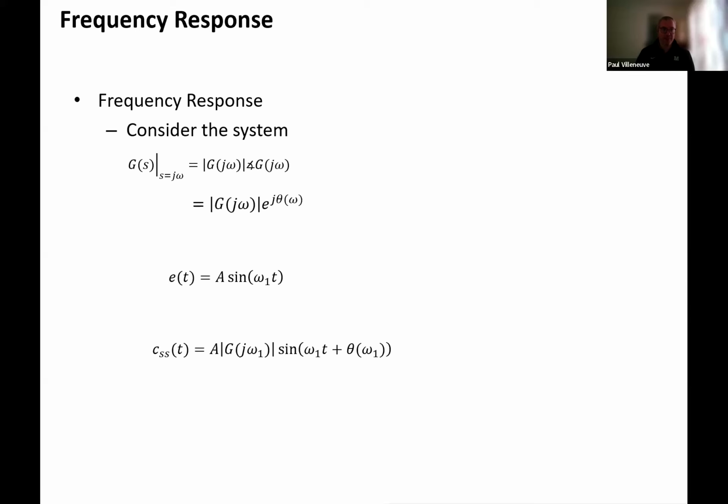That's why they're complementary. All right, so let's look at a system, any old transfer function. And we're just going to represent our closed loop transfer function. So if you want to subscript this with a closed loop, you can see that that is our closed loop representation of any old system. And we've been developing transfer functions this entire semester that are a function of the Laplace variable S. But if you recall, and it has been a while since we looked at it, we did introduce the Laplace variable as the complex representation of frequency. So what we can do is substitute S equal to j omega.